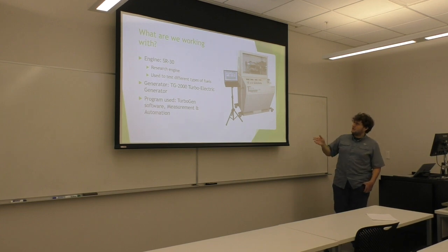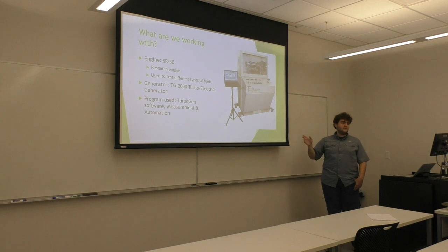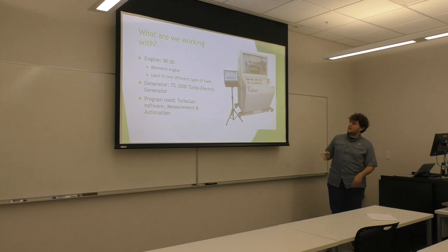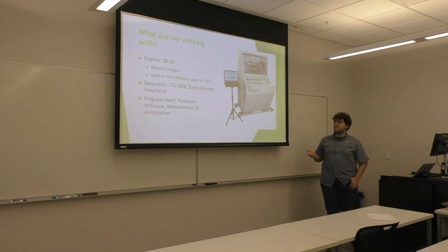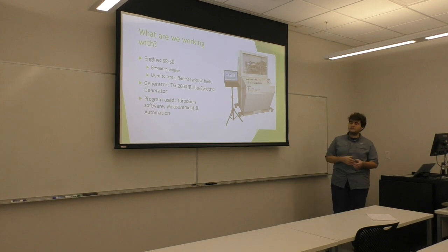There's a computer over there with our software that will be recording the data over time. There are different sensors throughout the system at the inlet, after the compressor, and after combustion, measuring the pressure and the temperature. We can then use thermodynamic air tables to find the enthalpy for each stage, so we can find the power transfer at different stages.